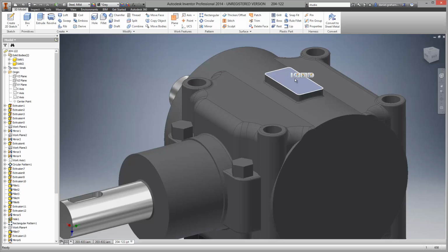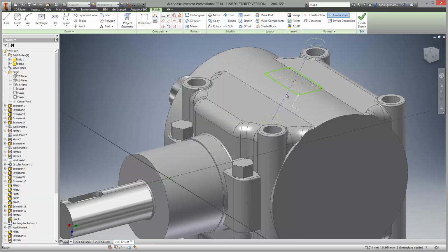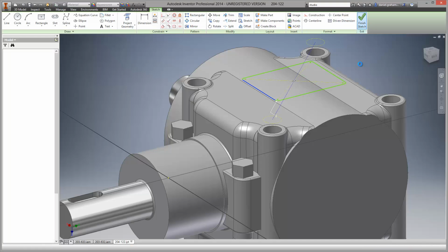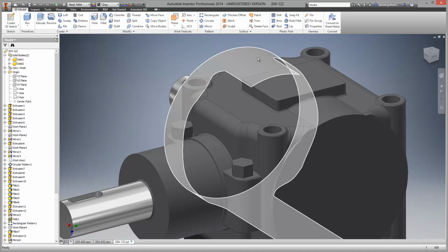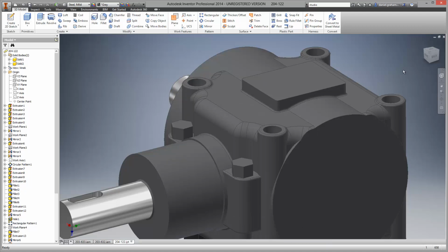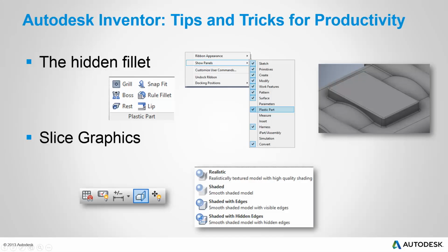So if, for example, I want to make a change to this, and I'm going to go back to this, and I'm going to say that this design is going to be wider, and then I rebuild this, notice it's very robust in terms of now my fillet still maintains that rule that I've applied that applies a fillet everywhere where that feature hits the boundary of the part.